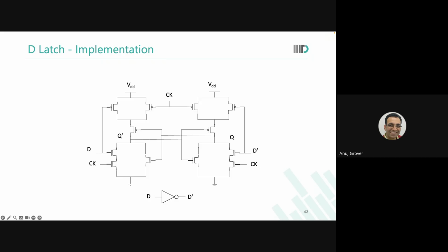That VDD is actually coming at the, that is, the NOR-like parallel transistor structure on top, VDD is always available at its base. So there are 4 transistors in this cell which practically do nothing. They are always just transmitting what was above. Is it not?